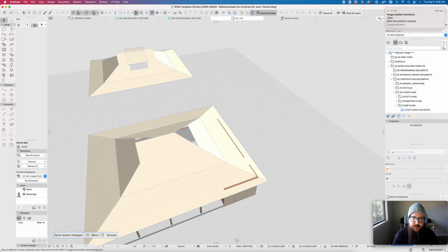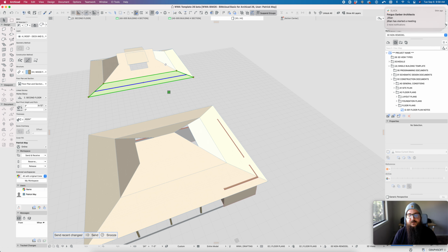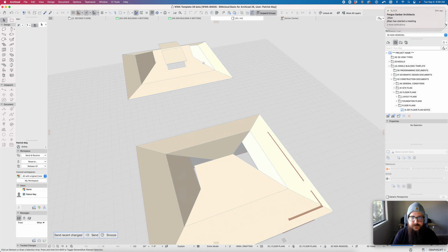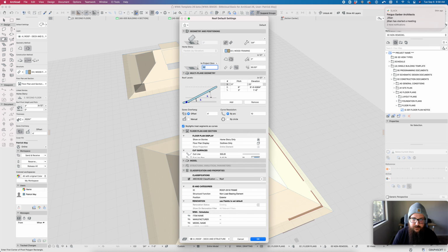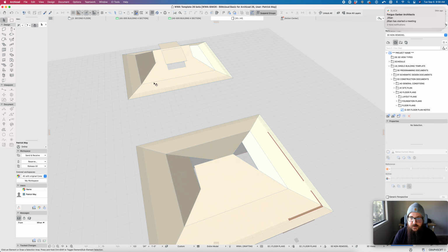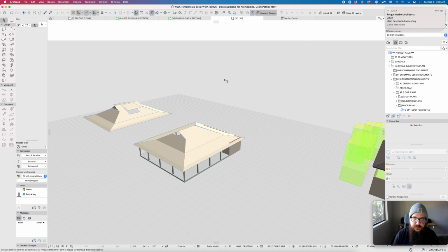We'll pull that up over here. That's right, we split that out, where with the multi-plane roof, you can go to the settings and say that the roof overhang universally for this whole roof is 4 feet or 3 feet or 2 feet or whatever it needs to be. Gives you the ability to adjust that. But it really depends on the complexity of the roof.